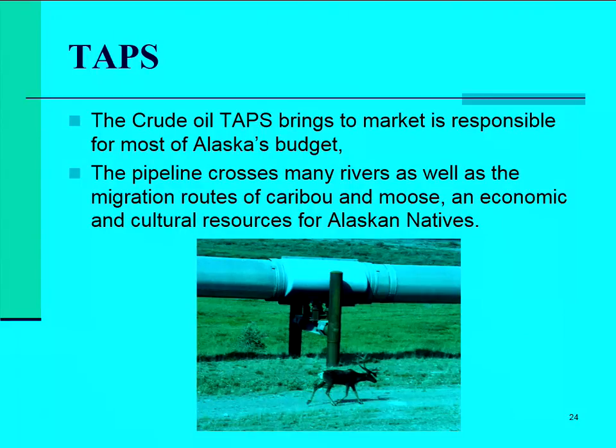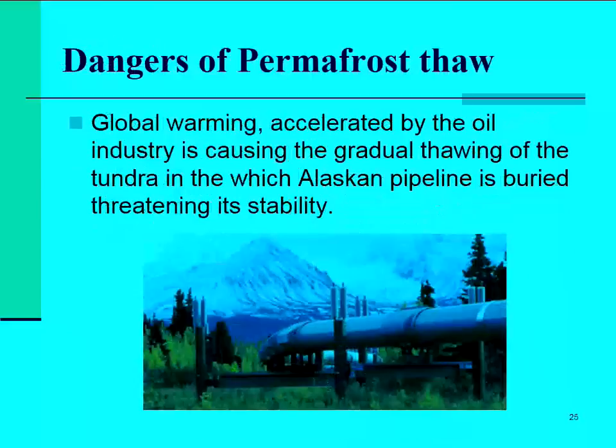But there's also issues over what impact the pipeline will have on the ground itself if it's carrying products which are quite warm, and will they cause the ground to warm up. So as I say, the reason why the permafrost melting can be an issue is because it can change the shape of the land. You know, bits of it can sink and the pipeline potentially could collapse.